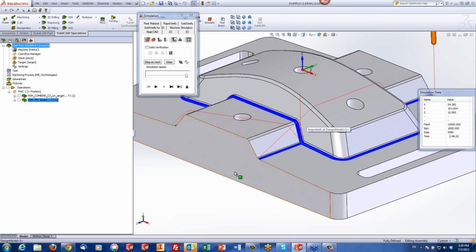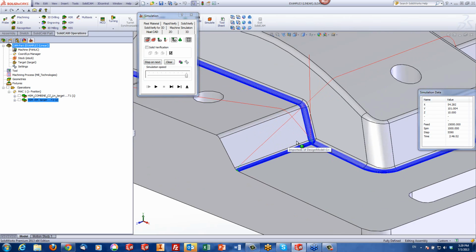If you measure your tool correctly on the machine, it'll actually look as if this entire surface, together with this surface over here and the radius, was machined with one tool only. You won't see any kind of mark between the two operations that you did over here, because this works extremely smoothly on the part itself. Now, let me just go back into the operation.